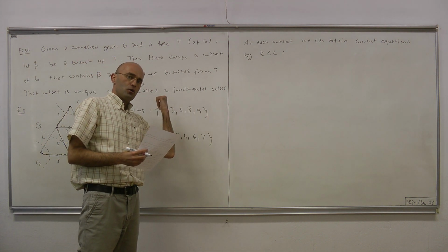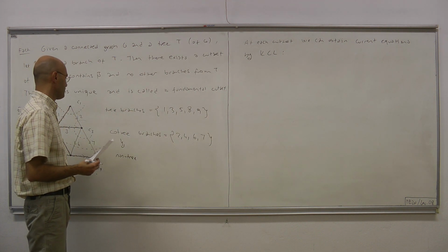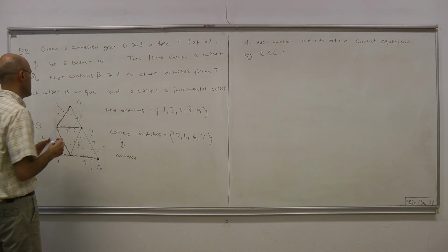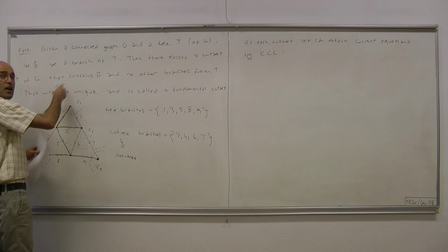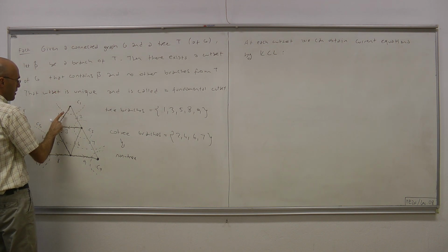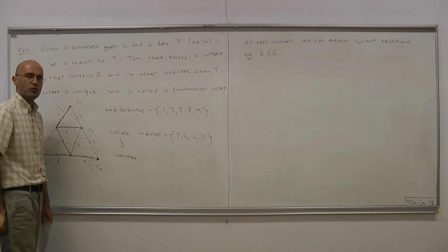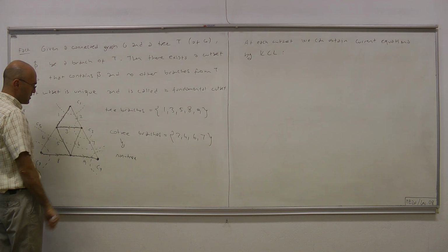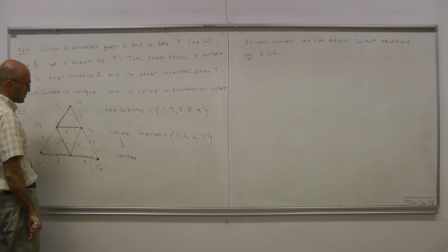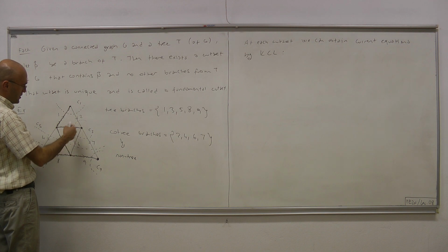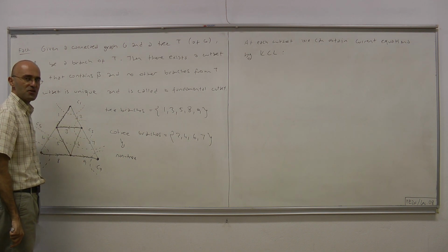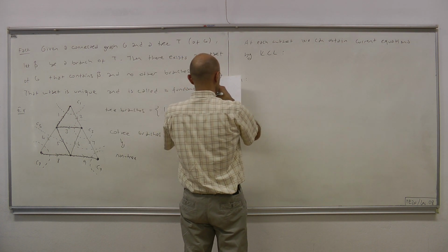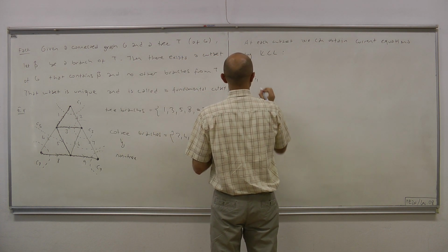And now, those cutsets we will use to construct our so-called closed surfaces. For C1, you can consider this as a closed surface, therefore incoming current I1 must equal outgoing current I2. So this cutset gives us the equation I1 equals I2. This cutset, for instance C3, we can consider as a closed surface. I2 must equal I3 plus I6 plus I7 and so on. So let's go cutset by cutset and write the equations.